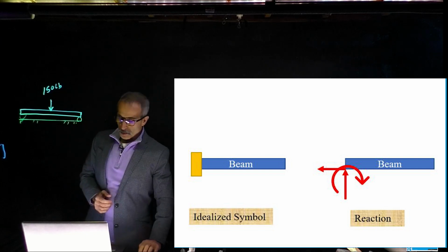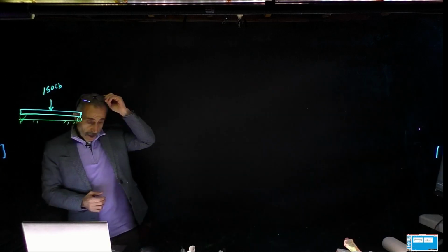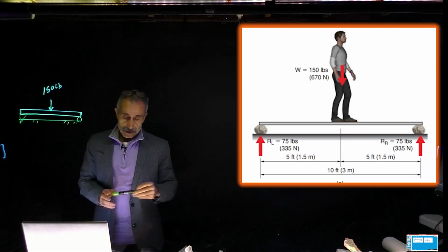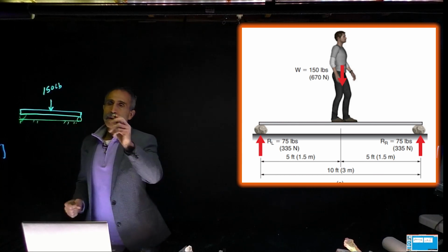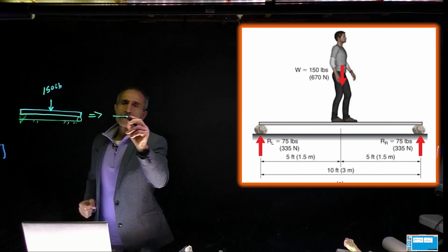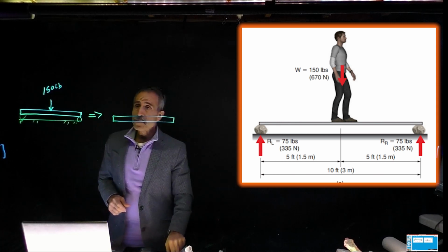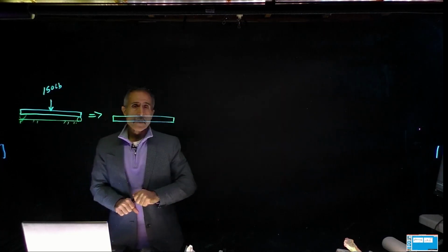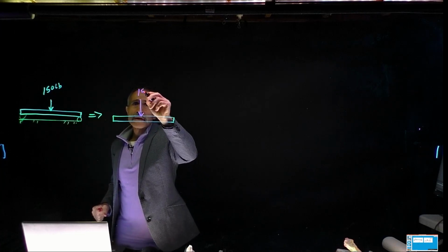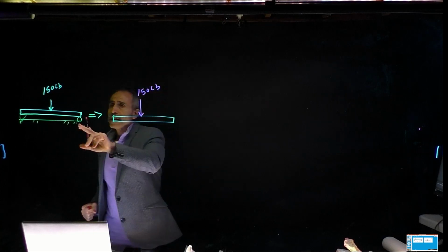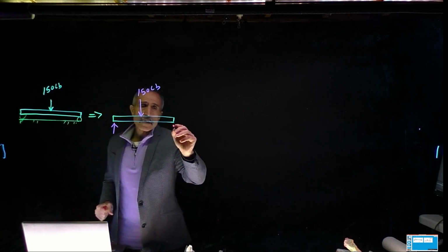All right, let's continue with our first problem. Here we have a 150-pound force down in the center. One of the first things we do when we want to solve this is draw a free body diagram. If this is my beam right there, I'm going to put my forces right here. I have my center force, which is 150 pounds. And then I have 2 rollers, remember how we symbolized these. So there is only one reaction here and one reaction here.